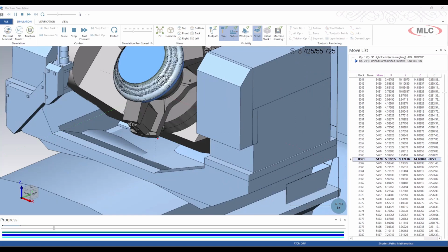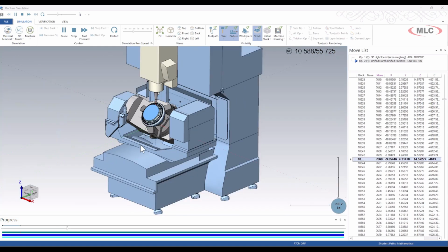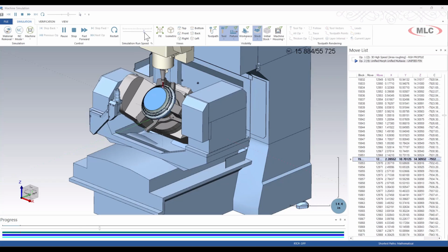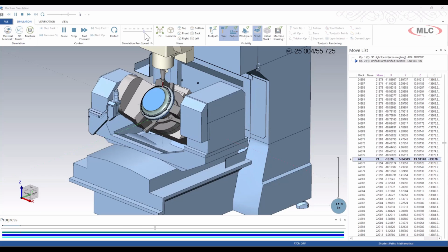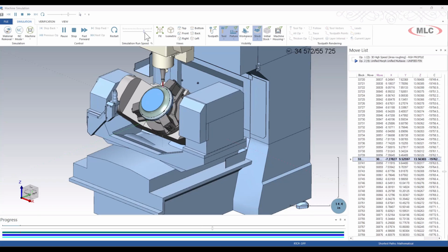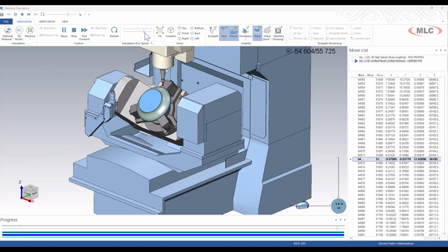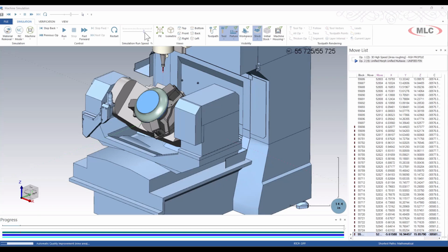As we zoom in, you'll notice that the distance between the actual trunnion and the machine itself does not move. So it's only advancing forward in the y-axis. This is going to be due to the lock that we have at that 45 degree. This is keeping it at a 4-axis operation.